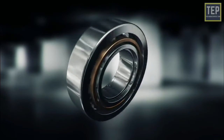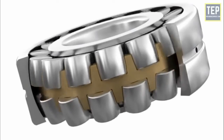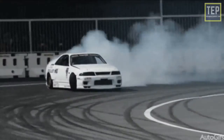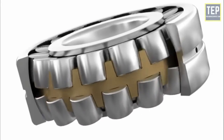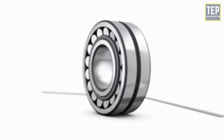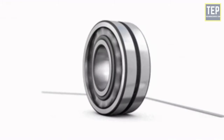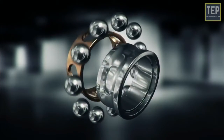Rolling element bearings contain rolling elements in the shape of balls or cylinders. We know that it is easier to roll a wheel than slide it on the ground, as the magnitude of rolling friction is lower than sliding friction. The same principle is at work here. These bearings are used to facilitate the free movement of parts in rotational motion. Rolling elements carry the load without much friction, as sliding friction is replaced with rolling friction.